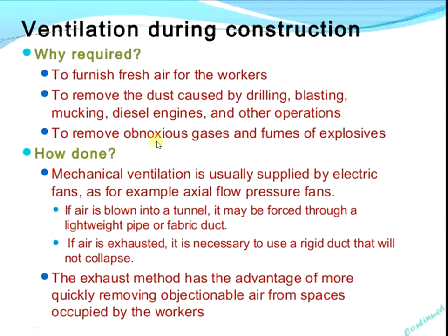To remove obnoxious gases and fumes of explosives. Next, how is it done? Mechanical ventilation is usually supplied by electric fans, for example axial flow pressure fans.